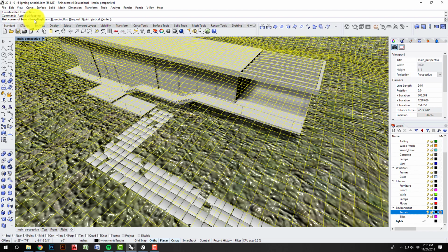and you can see up here right now it wants me to apply a first corner. So I'm basically making a bounding box, which is going to define how big it is. This can also go anywhere. So I'm just going to click here, and my project is actually in inches, not centimeters, but I know that 200 centimeters is about 78 inches. So I'll type in 78, enter, 78, enter, so length and width is 78. And for height, I'll also do 78. It shouldn't matter that much because it's a flat surface.